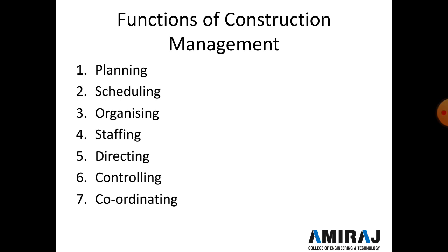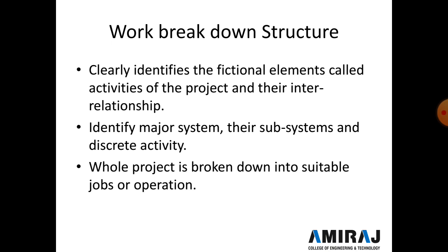So these are the important topics of the construction management subject, and now next we start with a new topic, work breakdown structure. So what is work breakdown structure? The work breakdown structure is a division that clearly identifies the functional elements, called activities, of the project and their interrelationship.